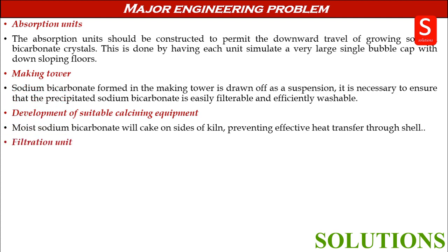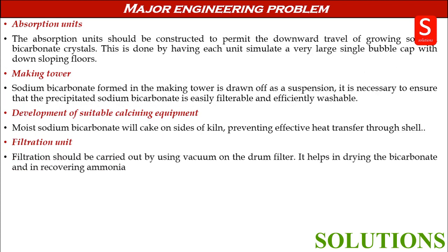Filtration unit. Filtration should be carried out using vacuum on the drum filter. It helps in drying the bicarbonate and in recovering ammonia. Ammonia recovery.